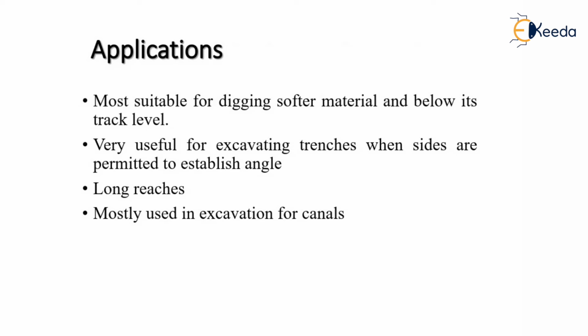Now, what are the applications of the dragline? The dragline is more suitable for digging softer material and below its track level, while it is very useful for excavating trenches when the sides are permitted to establish an angle. Now, the dragline has the possibility of long reaches, so it is best suited for such applications. And next, it is mostly used in the excavation of canals.